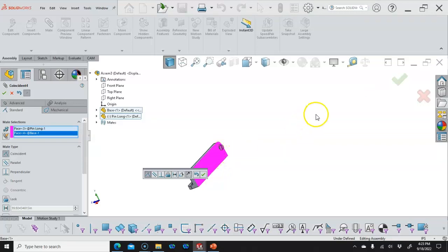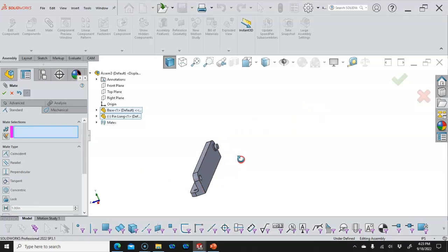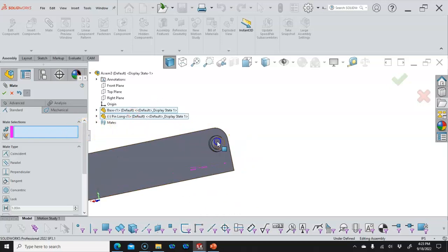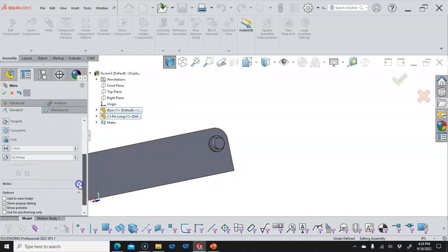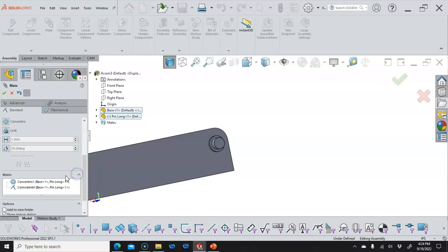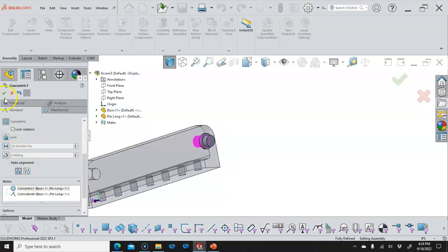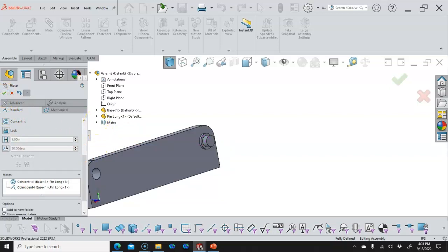All right, so when I pick the inside face of the flange and the back face of the base, that is going to bring those two together. And other than it can rotate, which we can't even really tell that it rotates, but if I had caught the coincident, and if we pull this out, or I'm sorry, the concentric is the one with the circles, and when that is clear, if I lock the rotation, I think it'll let me back into that. We'll double check it real quick.